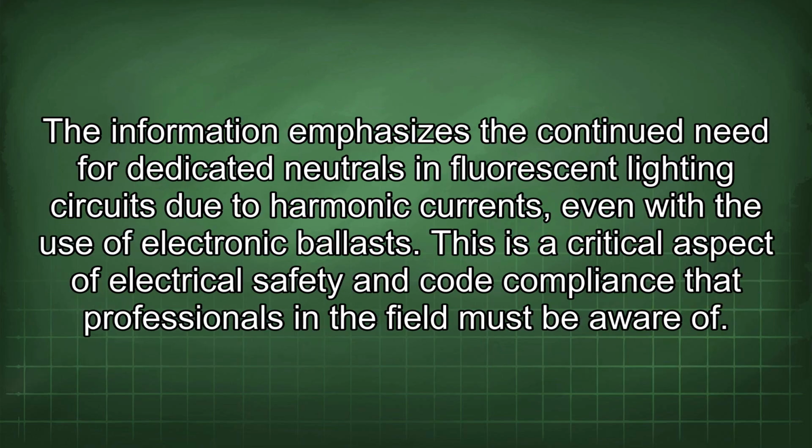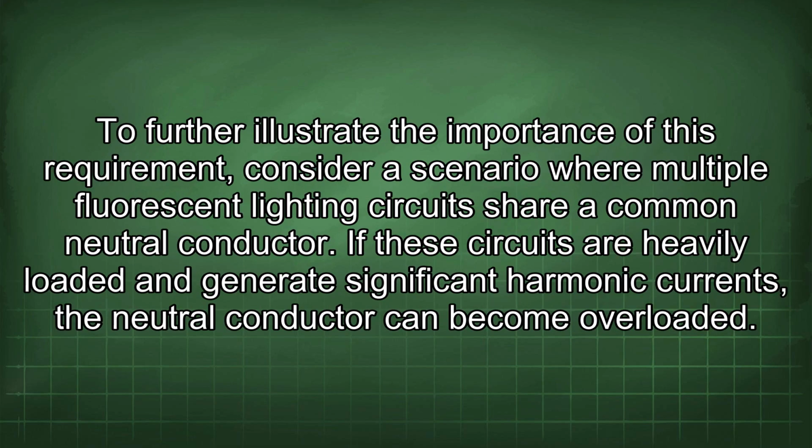The information emphasizes the continued need for dedicated neutrals in fluorescent lighting circuits due to harmonic currents, even with the use of electronic ballasts. This is a critical aspect of electrical safety and code compliance that professionals in the field must be aware of. To further illustrate the importance of this requirement, consider a scenario where multiple fluorescent lighting circuits share a common neutral conductor. If these circuits are heavily loaded and generate significant harmonic currents, the neutral conductor can become overloaded.